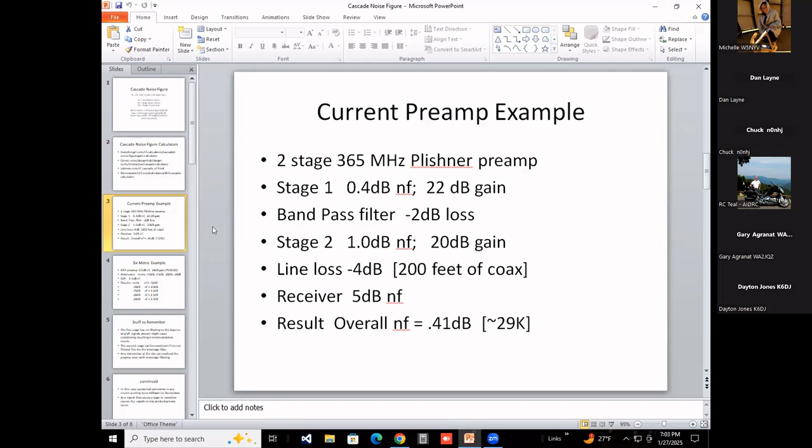So if you think of the noise temperature of all the parts up there, if it were a resistor, it would have a Kelvin temperature of 290, but without any resistor components or lossy components in front of it, the noise figure of modern-day transistors and ICs can get well below 1 dB. In fact, we can get much lower than what we actually have right now, but these are fairly common off-the-shelf parts.